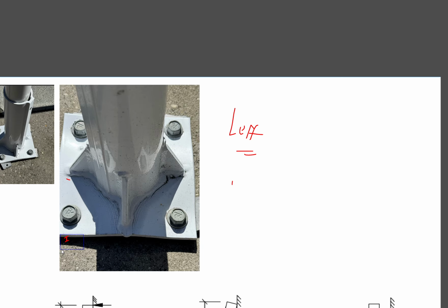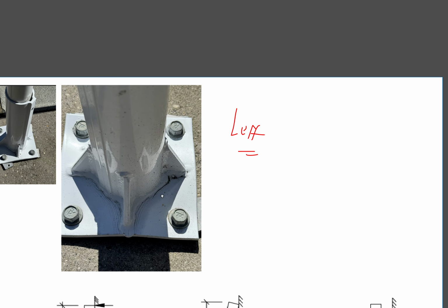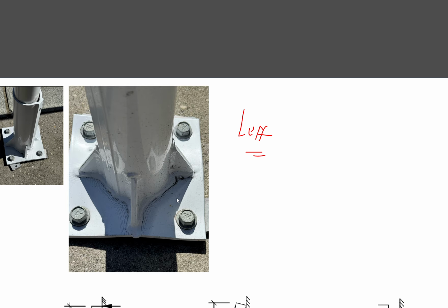And the second thing is the mechanics associated with it, because you are yielding your base plates. Let's say your plate yield stress is 300 MPa. Your plate has a length and a breadth, so L and t. The stress of the plate yielding is going to be your moment divided by your section modulus.